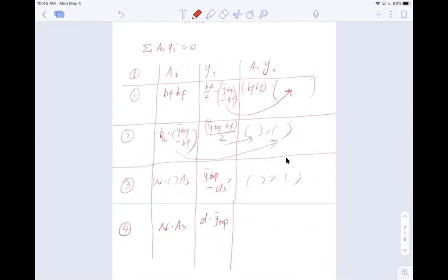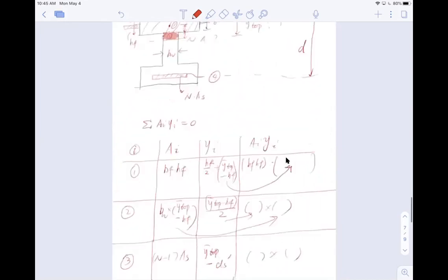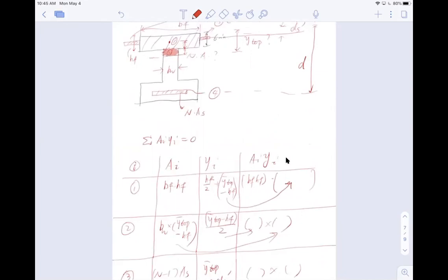Now one thing: for the tension, this is actually a negative distance. You understand why? No. Okay, so this is the neutral axis. On top of the neutral axis, y is positive. Below it will be negative. Since the rebar, which is part 4 converted, is at the bottom here, that will be negative. And this should be covering the mechanics of the curve.